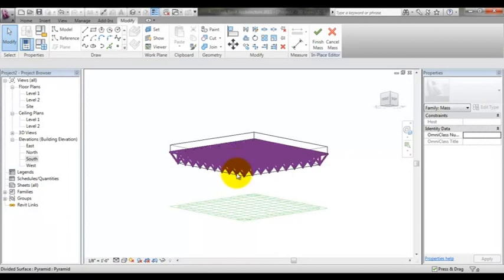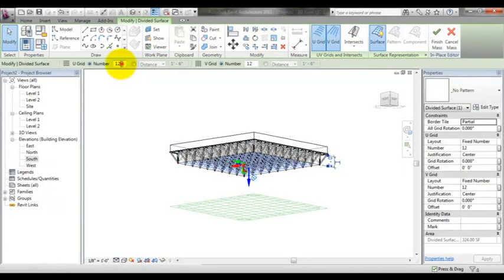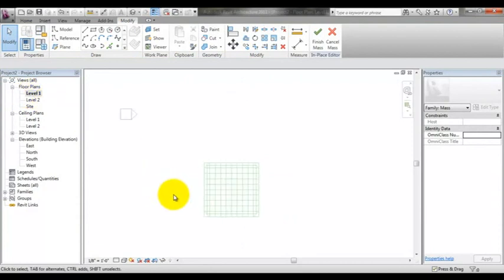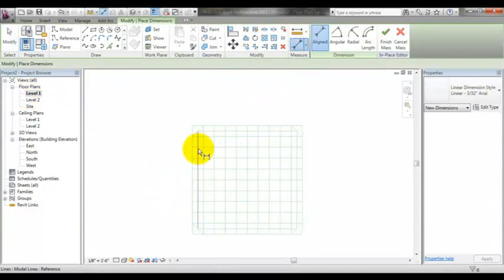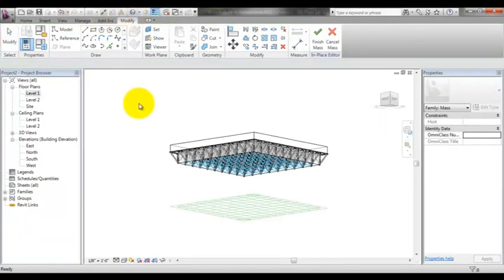Now this is to put the extra set of rectangular framework. So to do that, I need to create one more family of rectangular framework. I'm dividing this to 9 parts because when I measure this between the 2 points, it is 18 feet. To have 2 feet by 2 feet, I need to have 9 divisions between them.